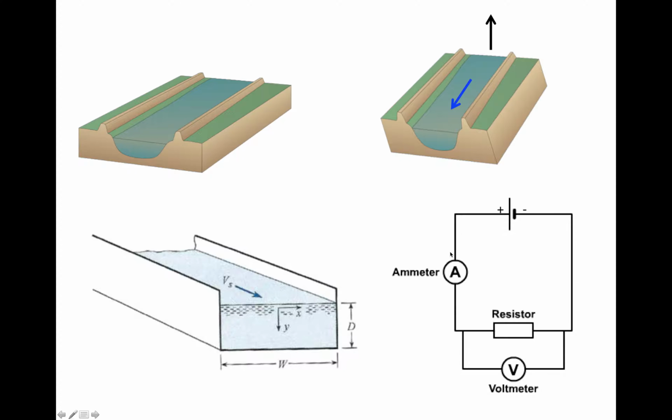If you are trying to measure the current, but the measurement instrument itself is going to disturb the circuit, then it's not a good thing. You are not getting an accurate measurement. So the ammeter has close to zero resistance, and it's not going to change how the current actually flows through it. So if there's no resistance through a certain segment of the circuit, from this terminal through the ammeter before it reaches the resistor, through the entire segment there's no resistance.